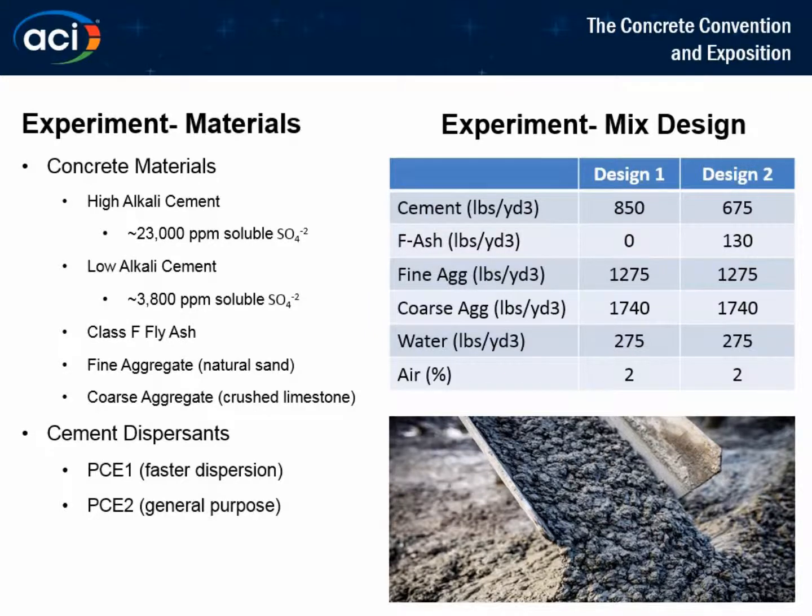So we wanted to push the extremes and really start to identify how the purposeful manipulations do in fact impact these designs. We looked at how these PCEs perform as a function of both the cement chemistry and the dispersant polymer characteristics. A constant paste volume was chosen to maintain a better comparability between those two mix designs.